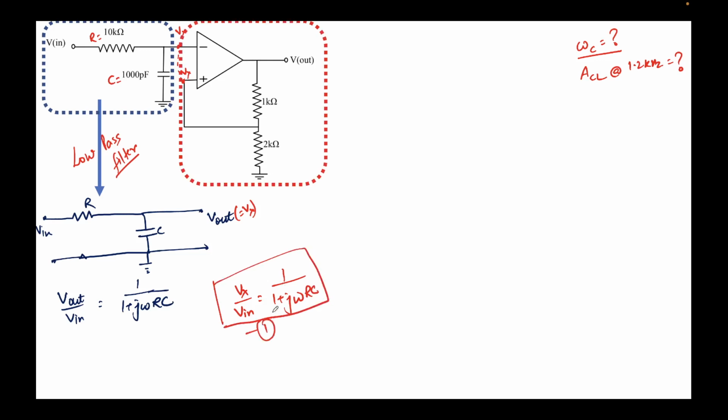Now let's look at the second half, the rectangle in red. Now this circuit is nothing but a positive feedback op-amp resistor circuit, and we can try to find the gain of this circuit. How? So we know this potential is Vx, because due to the virtual short, this point will also be at Vx. Now let's try to apply Ohm's law.